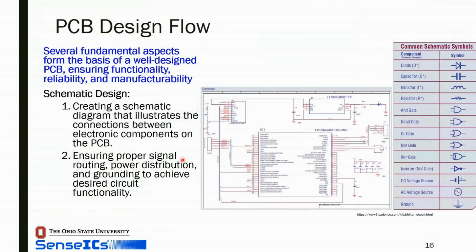Okay, so that's just one example of, if you're a PCB designer, you have to think about something called electromigration. You're going to burn up the board if you pass too much current, so you have to design the PCB traces to be wide enough to handle the current that's going to flow on your board. So anyway, just a quick example there.